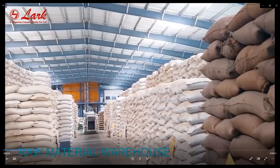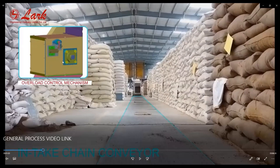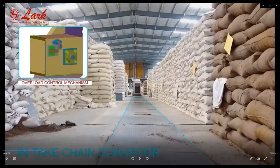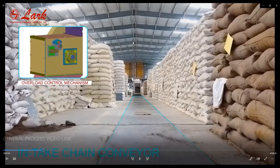Like this intake chain conveyor. One thing more, the new innovation that we introduced in the intake chain conveyor is the overload control mechanism. If there is jamming in the intake elevator and the labor have no idea that there is material stuck in the bottom of the intake chain elevator, but keeps on putting the raw material in the chain, what happens due to the jamming and the overload on the chain is that there may be failure in the gearbox, the scrapers, or the shaft, or the chain moving parts. The weakest part may fail due to the jamming.